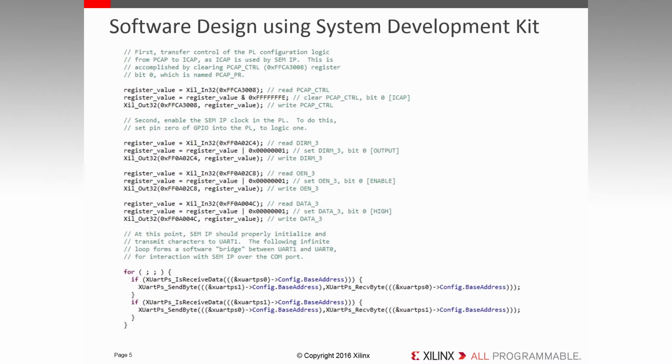UltraScale architecture SEM IP state changes are announced by strings that start with the letters SC, and similarly, the uncorrectable and essential flag changes are announced by strings that start with FC. Additional event details are provided in the notifications. Please take a look at PG187 if you want to learn more about their format.